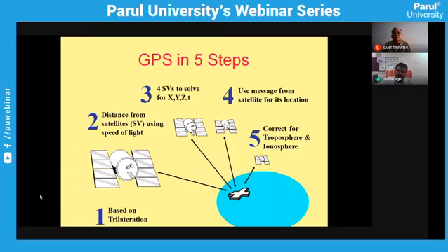clock. So whenever you start using GPS, first of all we have to check whether our handheld GPS has the proper day and time, and whether it is getting signals clearly at the particular position. Based on that, we will be able to locate where we are standing. This is the basic triangulation method used for positioning a particular point.